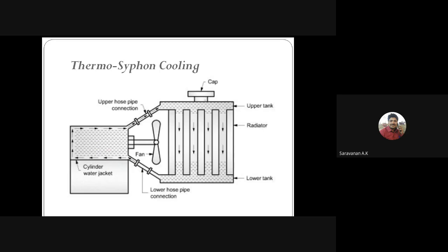In this radiator, how does the water travel? The water travels in this direction, and while it travels, here we have some aluminum fins. The fins have a zigzag shape, so that will increase the heat transfer. That will increase the contact area, that is the surface area.